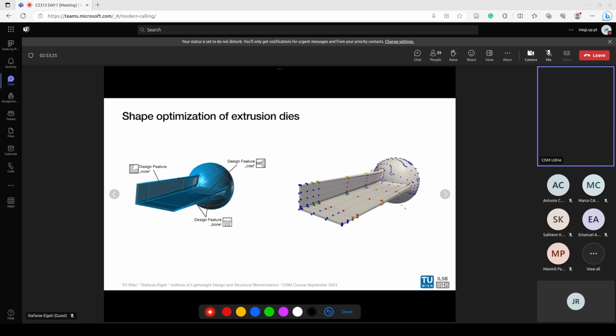And why did it happen exactly like this? Because we talked to practitioners and we asked them, what would you do? And they told us that basically they have three kinds of measures that they would take. So first of all, they would adjust the slope here of these legs. They would create something that we call nose, so a structure that prevents cross flow between the two legs, and something that we call bone, which is this bone-like shape that is created here, where because of the wall adhesion, the material is slower. So you want to get more material into these edges where there's higher wall adhesion.